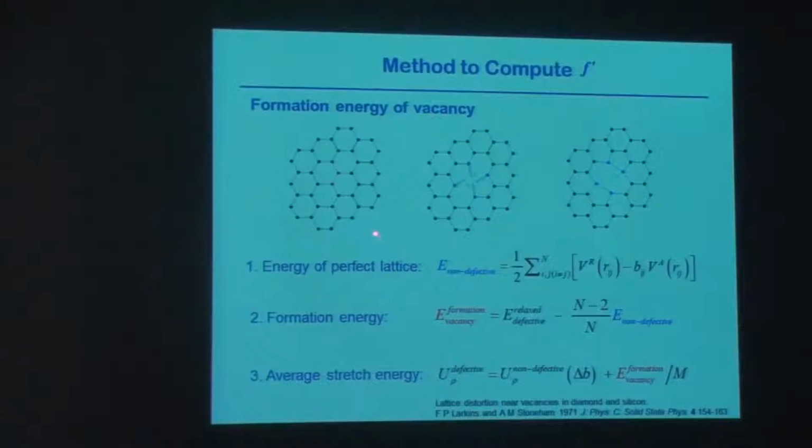So we have a graphene, this is a 2D sheet, hexagonal pattern, and think that we are going to create a di-vacancy. So these two atoms, which are color-coded in red, they're going to be kicked out. So when you drop them out, there are two atoms that are less there. These bonds that were there, they are dangling bonds. Some new bonds will form, and the relaxed position of these atoms around this defect is not exactly same as in here. So question is, what was the force that was required to perform that?